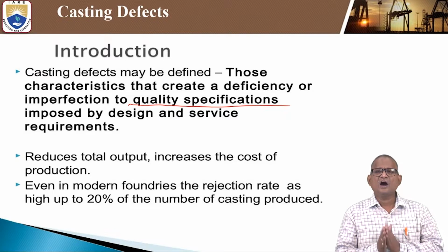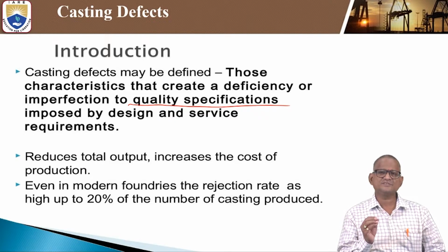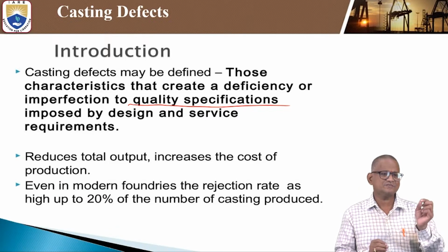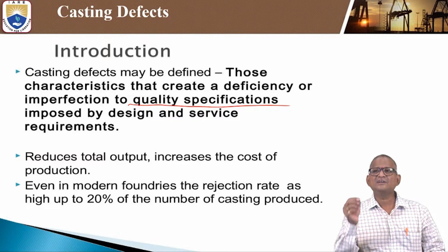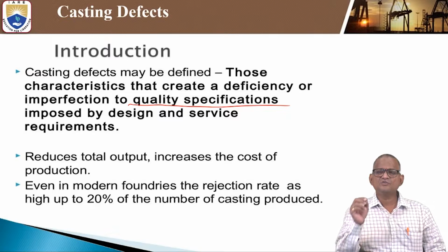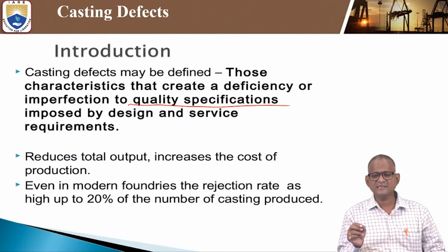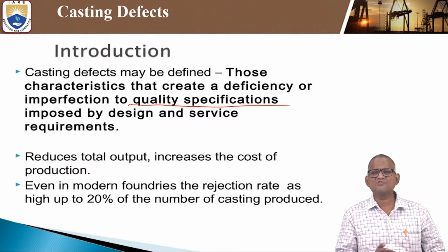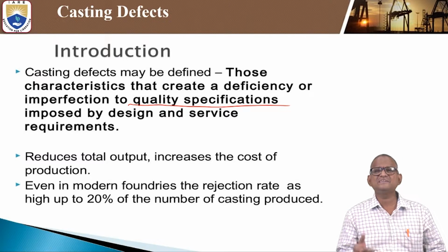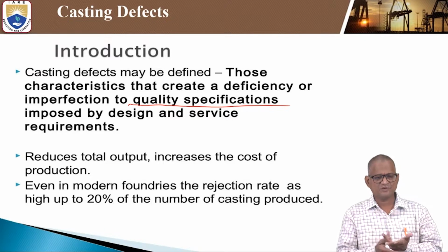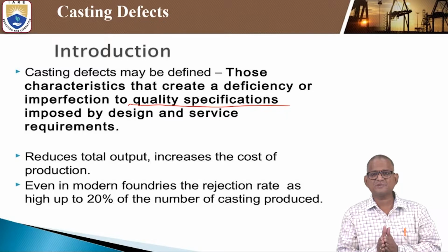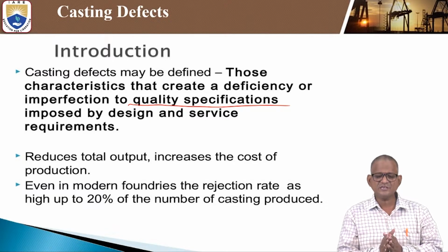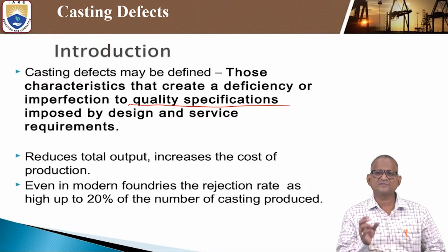So in the casting process you should take each and every parameter into account, starting with the pattern design through to the shot blasting and finishing of the casting. You should give certain instructions on the requirements to have a quality or sound casting, and these should be given every fortnight or every month as repeated instructions to the various departments, either the foundry department, fettling department, shot blasting department or testing department. Only then can we reduce the cost of the product.